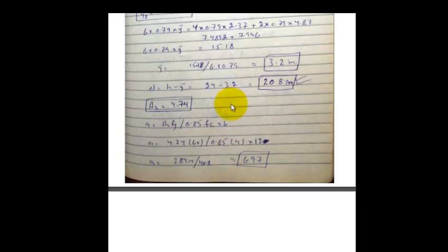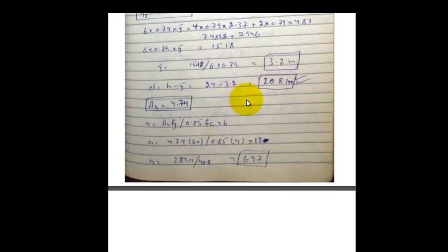We found the effective depth at the start of the lecture, but that effective depth was an assumption. This is the accurate effective depth, where d is equal to h minus Y dash. h was 24, Y dash is 3.92, so we get 20.8 as the effective depth, but we took the assumption which was 21 inch. Not much difference.